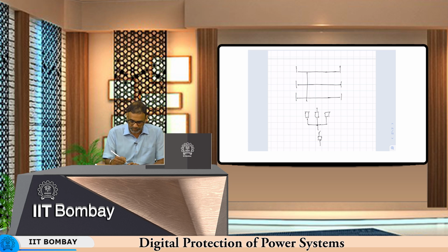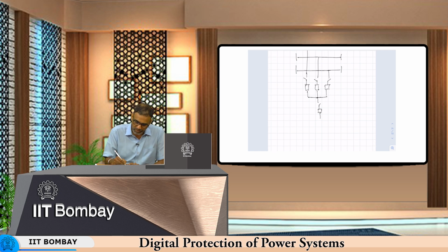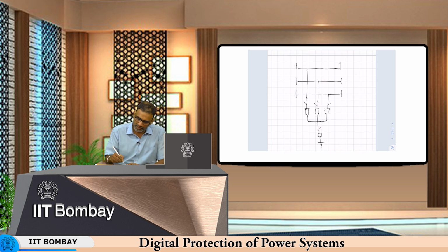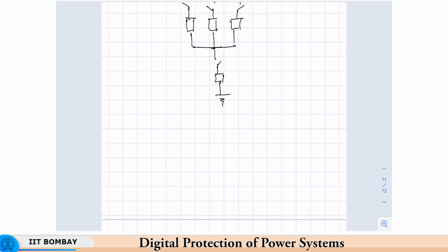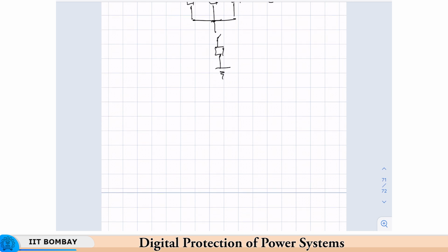Okay. Now one statement that we will make before we start off is that irrespective of the type of the fault, what we are seeing here is the apparent impedance, because it is V by I of that nature, since we are taking the V and I inputs. So the statement that we are making here is, irrespective of the type of the fault, the apparent impedance as seen by the relay, or ZR, will be equal to x, which is the per unit distance at which the fault occurs, into Z1, which is the positive sequence impedance of the line.